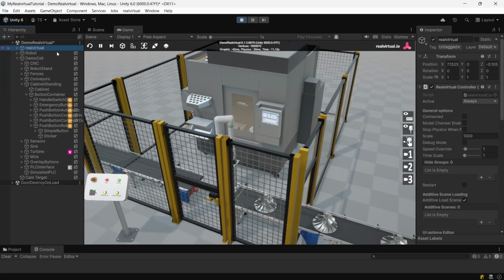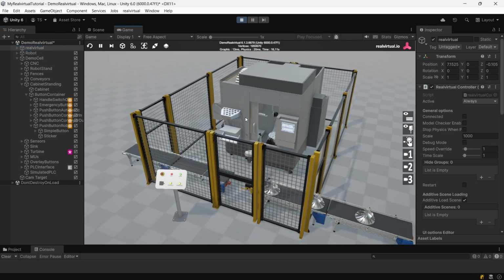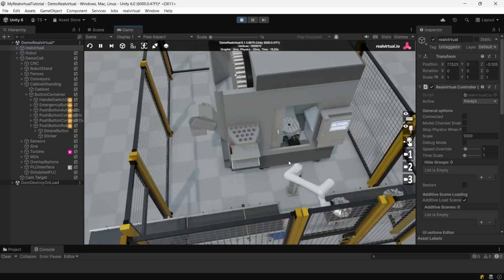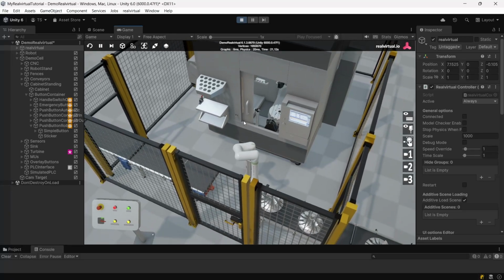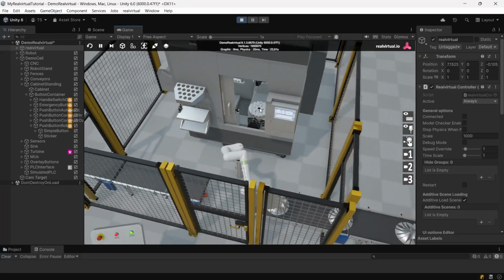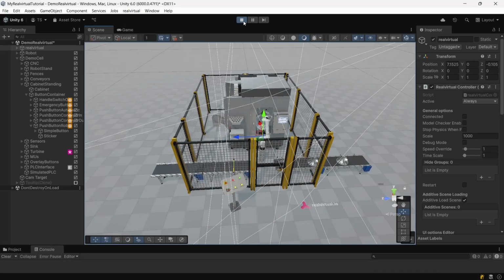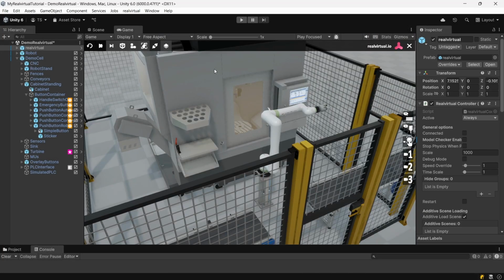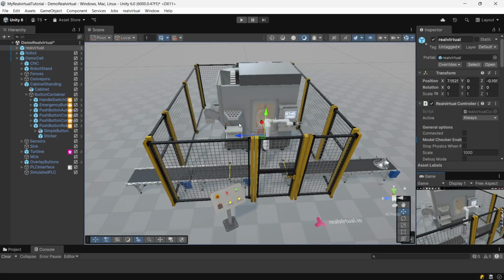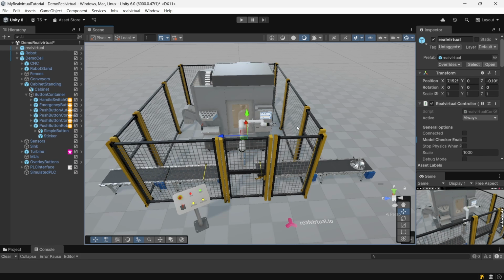The navigation is part of our functions and it's included in the realvirtual standard prefab, which should exist in each and every scene you do with realvirtual. So that's the game and scene view navigation. Usually my advice would be to take this game window and make it small, because for editing and building up digital twins you don't usually work in the game view.